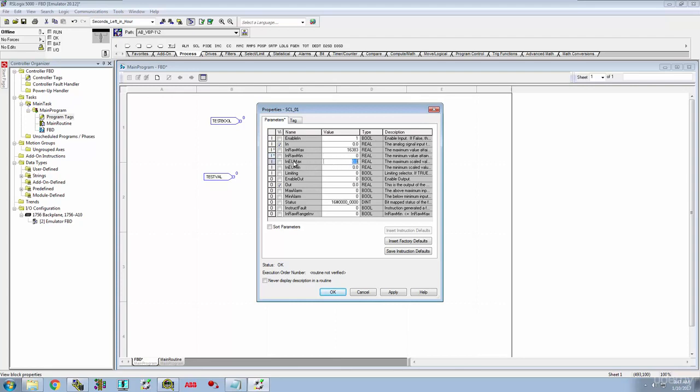And then we've got our NEU max and min. So that's our engineering units. Basically, that's talking about our scaled values. So let's say we're going to scale that from 0 to 100%. Well, here's our max, so we'll go ahead and set that as 100. We would set our min as 0. And then in here, we can put some alarms in here. And there's different things that we can do with this. But if we just set it up like that, already we're good.